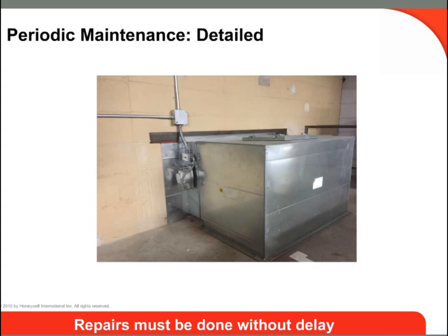After fire and smoke dampers are installed and the system is balanced, an operational test needs to be conducted under normal HVAC airflow as well as with no airflow. Do this by making the damper automatically close and verify that it closes with no obstructions or interference that blocks complete closure. If it is a fire damper with a fusible link, then remove the link during the test and replace it when it is done. If it is a smoke damper system, the test is done with no airflow unless it is a dynamic one. Then the test needs to be done with airflow.